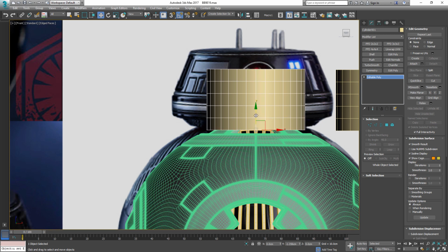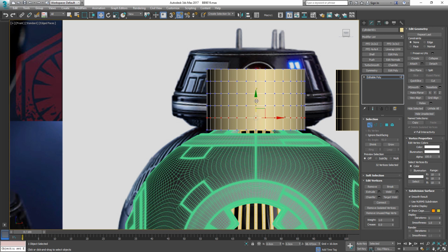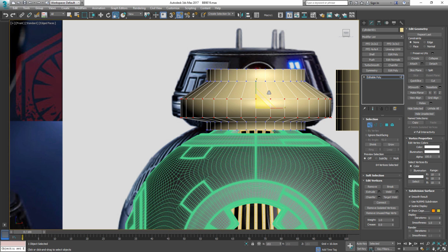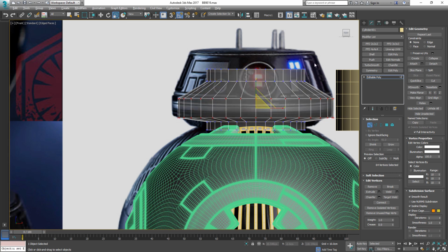And now we can make a polygon selection out of that, or an editable poly. And I'm gonna select these vertexes here and just shift them around a little bit. And now with that selection active, we can scale it here. Use the scale tool. And that one here, I also want to scale it, but in.